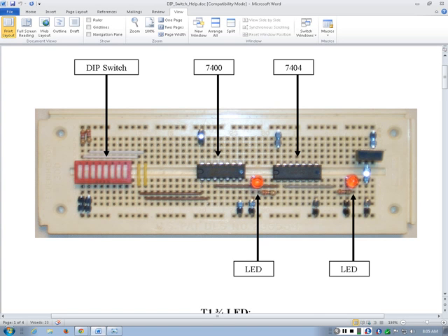So this is pin 1, pin 2, pin 3, 4, 5, all the way to 7, and then you go to here, that's 8, and read backwards 9, 10, 11, 12, 13, 14. That's exactly how you will read the IC numberings. And look at how we are installing the IC here. You keep your curve on the left side, and you are putting it in the middle, because you don't want all these pins to be short with all these pins.